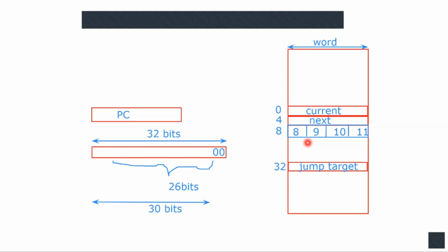So when you have a 32-bit address in the program counter, and you send that to access the instruction memory, your least significant 2 bits are typically ignored because we don't care about accessing individual bytes, right? So the address is always a multiple of 4. The byte addressing bits are always 0, because we are dealing with multiples of 4: 0, 4, 8, and so on.